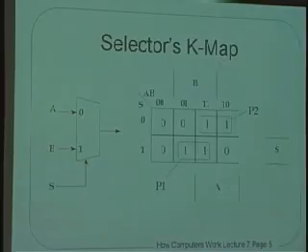Well, the first thing that you might be tempted to do is say, I want to make circles of product terms that are a power of 2 in size and as large as possible, and I want to use the minimum number of them to cover all of the ones that are in the circuit. In other words, I want to minimize the number of AND gates that I use. So you might come up with an implementation that looks like this.